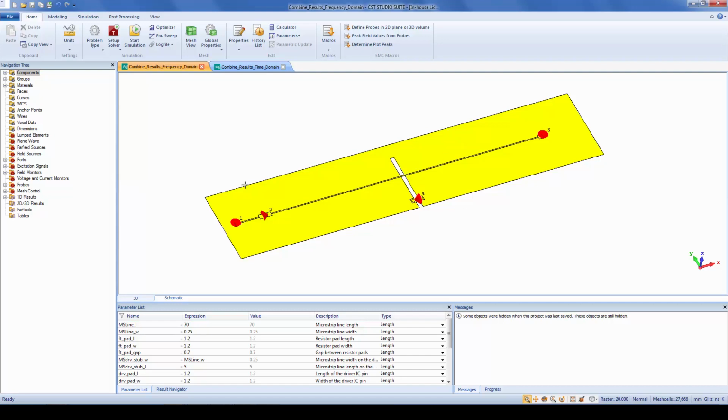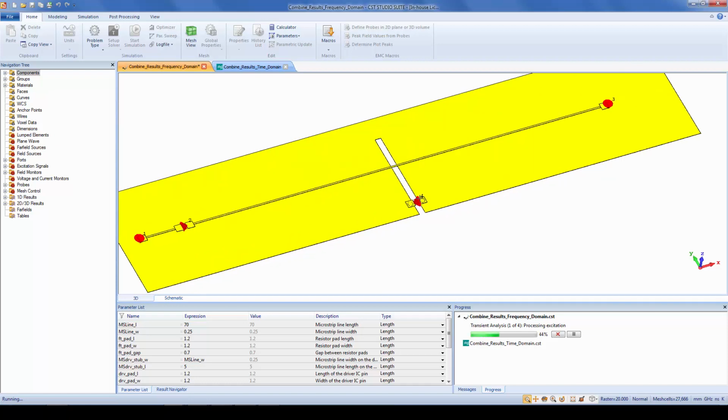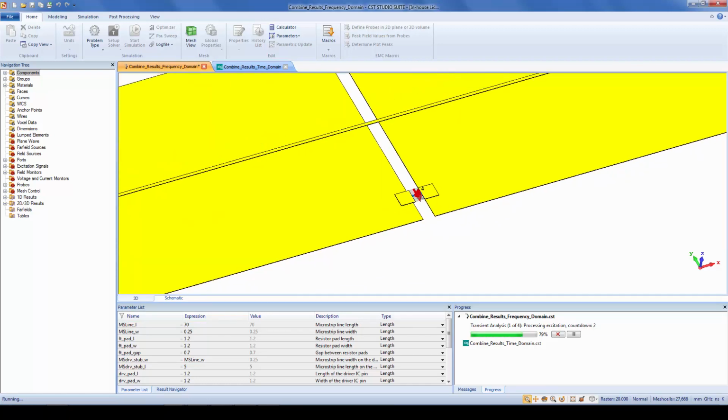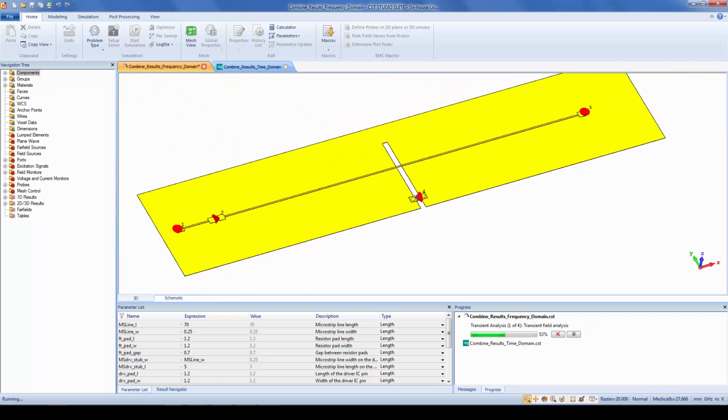So I have taken again my microstrip, but I put a hole in there. And first I simulate again with the broadband simulation, as I always did before. So I run it. Now I have to go through 4 different ports because I have placed a slot in here, and basically a bridge where I can put a component in order to short the slot, or keep it open. And because we want to see how this affects things, I have defined field monitors at 100 megahertz and 1 gigahertz, so we will see the surface current after it finishes.